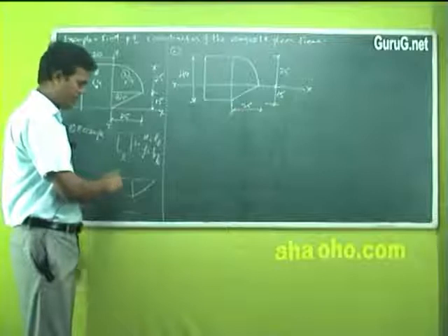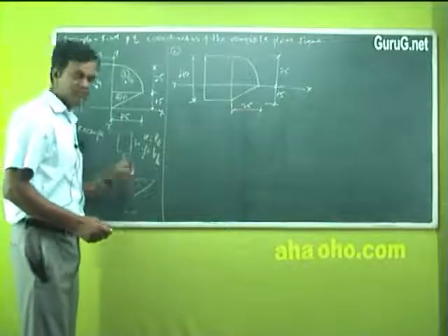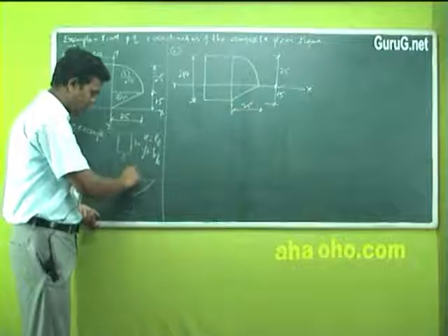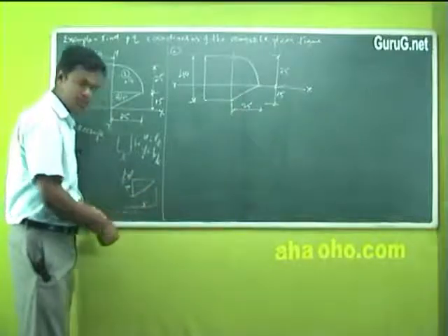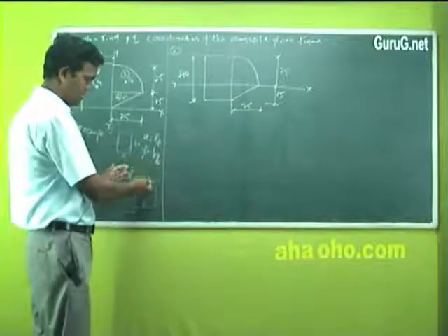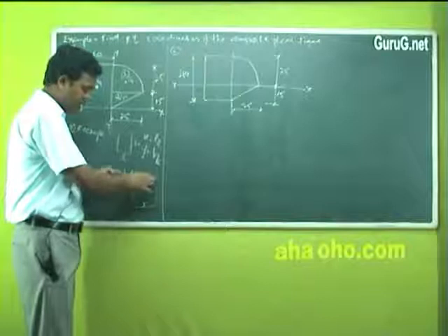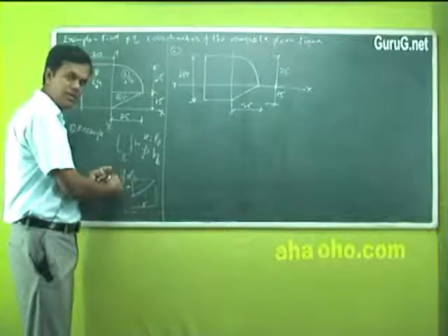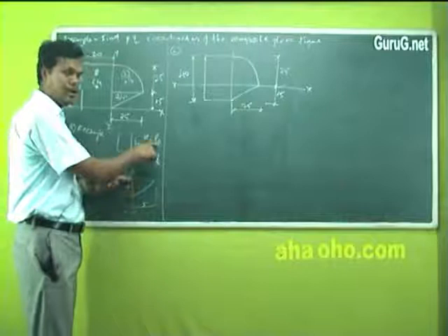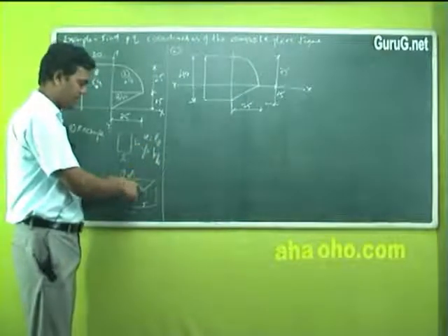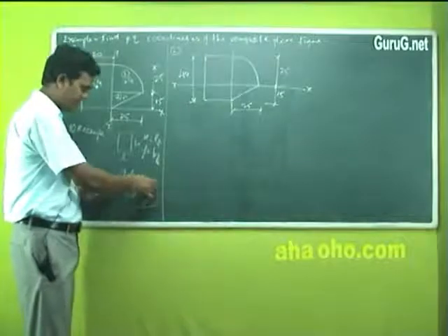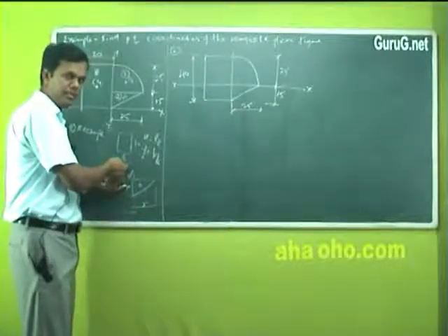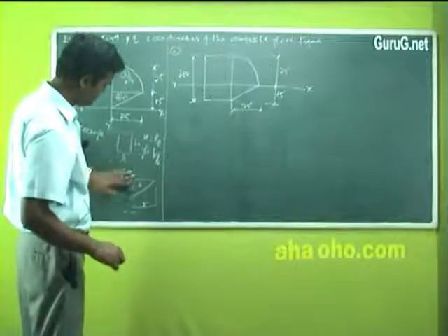We have already learnt, if you are writing the x values as per the formula given, if you go from the bigger end towards the smaller end, it is 1 by 3 into this length. This is length here, and height is this. Hope you can imagine how it is. If you tilt it, this is the bigger end, the total height, and this is the smaller end, is it not? So when we are calculating the x and y values, x means always with respect to L. So 1 by 3 of L will give you the x value here, to find the CG, if you are traveling from bigger end to smaller end. And if you want to go from smaller end to bigger end, it is 2 by 3 of L, right?